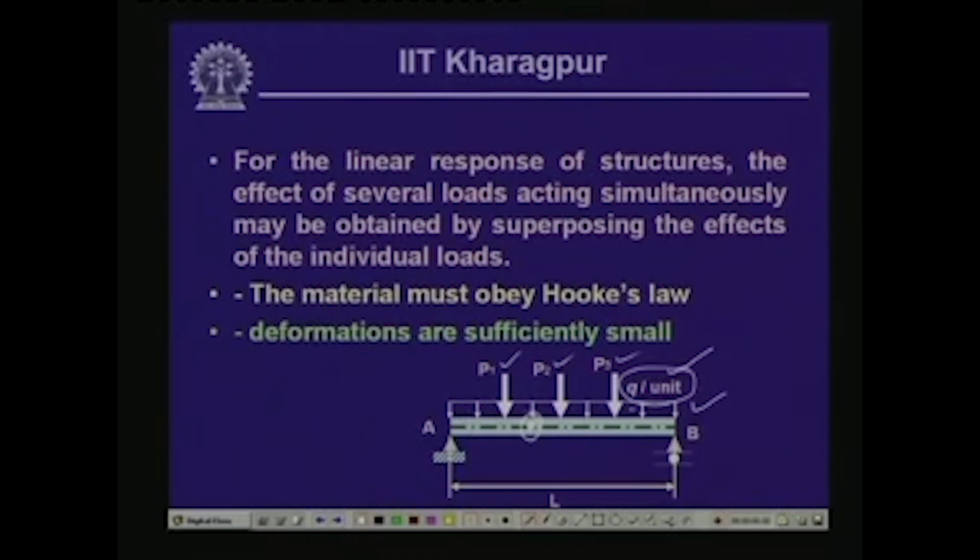Let us say the usage of differential equation of elastic curve. We can use differential equation of elastic curve which says that EI d2y/dx2 is the bending moment M, and we can employ that to evaluate the deflection at this particular point for general loading as shown. Also, we can evaluate the deflection of this particular point using the method of superposition, wherein we use individual loading. Instead of considering all the loadings acting on this particular beam, we consider the loads one by one and evaluate the deflection at this particular point for each individual load, and finally we sum them together to get the final deflection at this particular point.